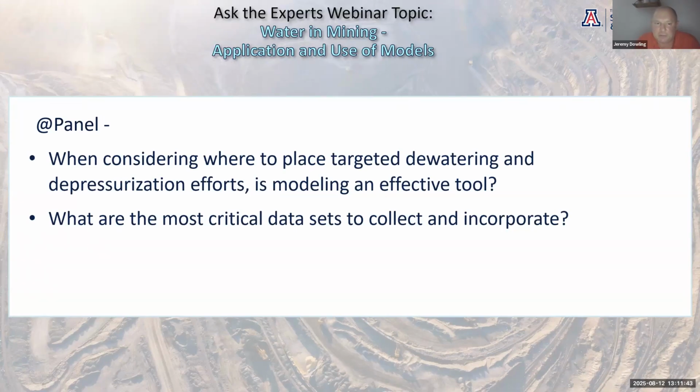They're often controlled by the major faults. So if you have a good understanding of the structural framework of the site and the hydraulic properties of those structures and of some of the major fracture sets, you can put that information into the model, and then you can start to get a reasonable level of reliability about where to place dewatering assets and how they'll perform within the open pit when they're operated.